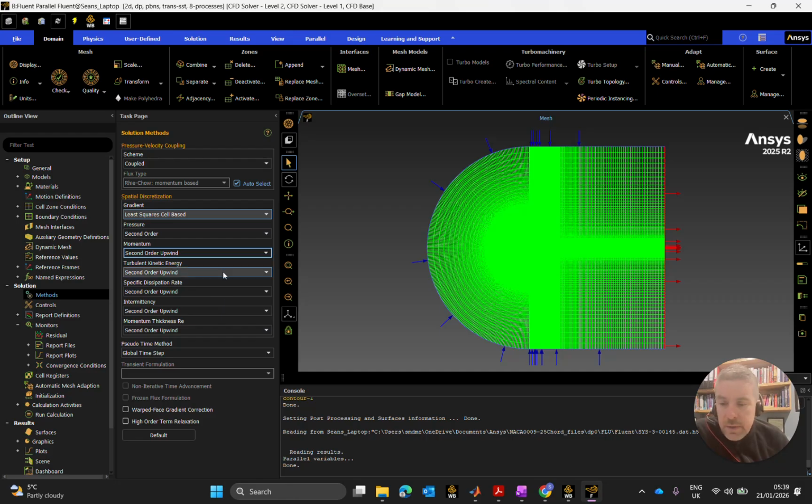Turbulent kinetic energy, yeah, there's very much the same sort of ideas on them, and nothing else down here. Everything else is second order. For a 2D airfoil application, an external flow application that has a good structured mesh, a second order approximation is good. It's solid, it's reliable. So that's why we're going to run with that.